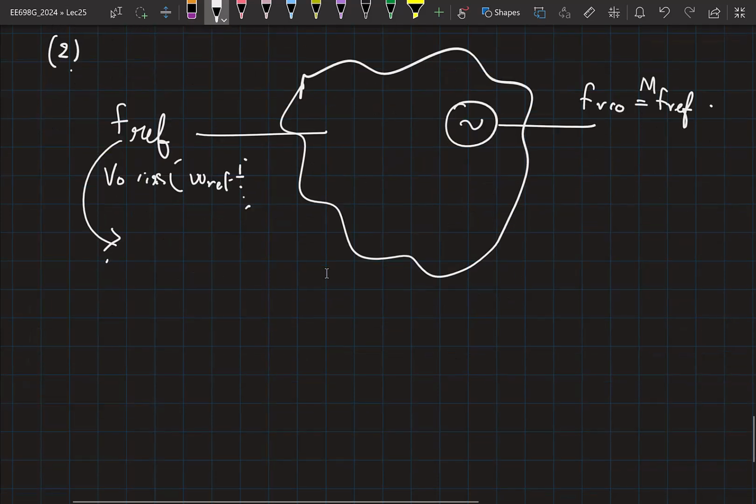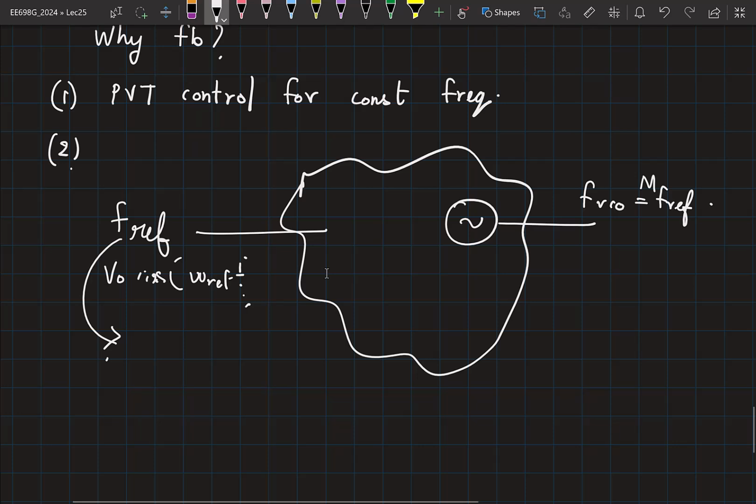So the clean clocks that we typically get are from crystal oscillators, especially the quartz crystal oscillators. Now they generate electrical periodic signals based on some mechanical vibrations inside, right? And one, it is slightly costly. Two, it is not available for all frequencies, right? And it's typically available for lower frequency ranges. It's not available for very high frequency ranges, part one.